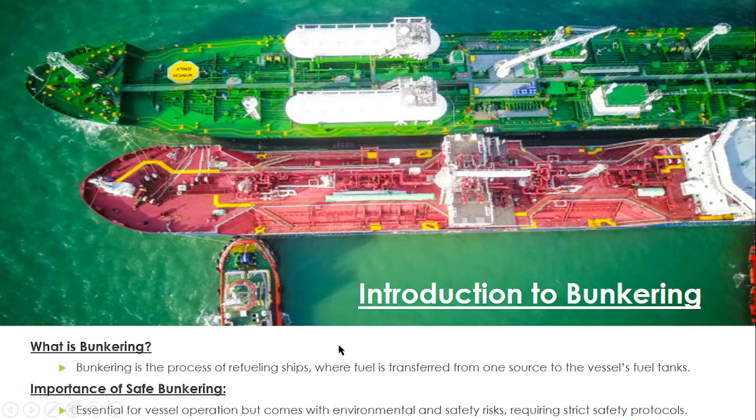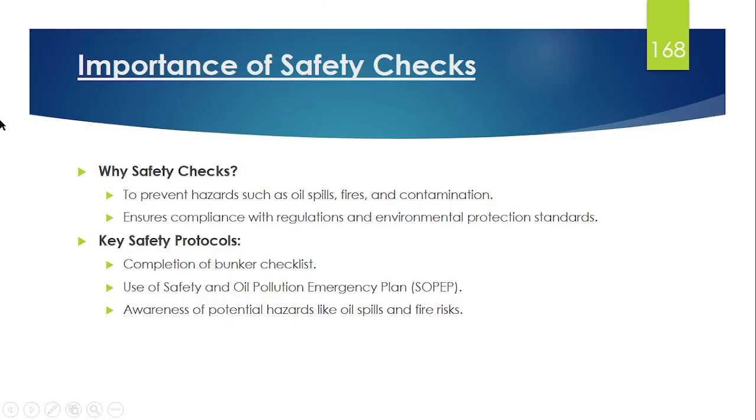Now, the most important concept of bunkering is that whenever you are transferring the fuel, here in this picture you can see the two ships nearby and they are transferring the fuel oil. Whenever bunkering is being carried out, the first thing is that it should be carried out as per the rules and regulations, and the second thing is that it should not pollute the environment and should be environmentally friendly. It means that we have to follow certain checks. We have to carry out certain checks before bunkering.